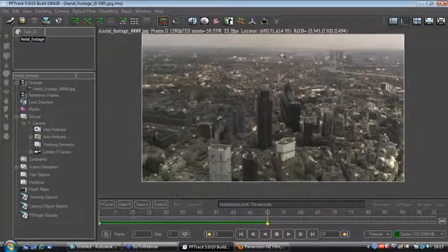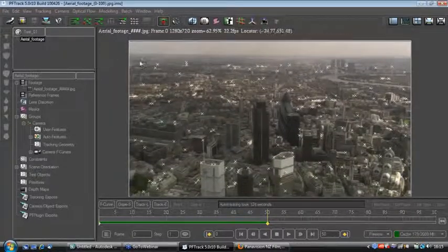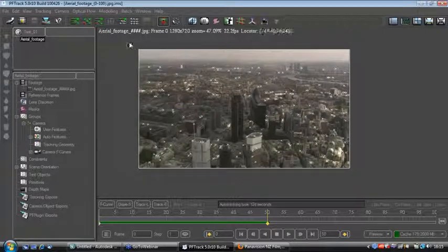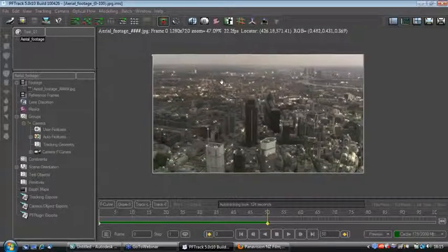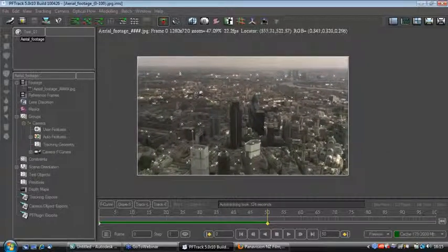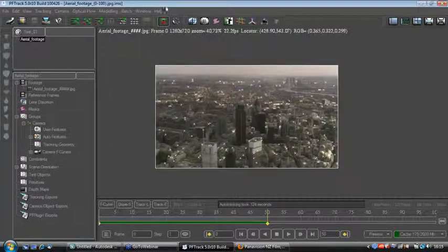Okay, so that's completed and it wasn't too painful to have that track those 50 frames forward and backwards. Now if I just move to the toolbar again, and currently we're in navigation mode, so just by using the left or right mouse I can pan around and then middle mouse to zoom in and out. If I move across to the little pick whip selection, I'm just going to drag a pick whip around the whole frame and select all of our current 2D feature tracks.